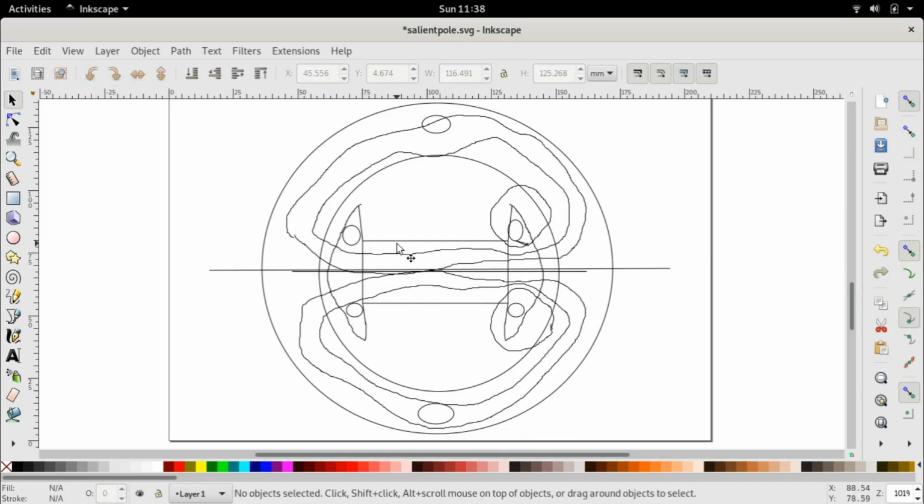Always, when we need to find out what's happening, we must examine how the flux path has changed. That is, if we take this one flux line, which is now in this new position, again we see exactly the same three segments. That is, there is a high permeability segment through the rotor, there is a low permeability segment through the air gap, a high permeability segment through the stator, and another low permeability segment through the air gap. Exactly the same three segments.